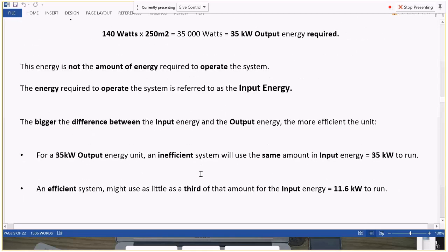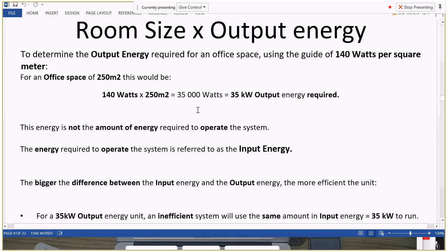And that's simply it. So if we were going to buy a split system air conditioner for this room, using the very simple check method, we're not going to be looking into the way our windows are facing, single panes, all that sort of stuff. We would go, right, how many square metres do we have in here? It's going to be about 7 by 7. Let's say we've got 50 square metres in this room, let's keep it simple. So we've got 50 square metres in this room by 140 watts.